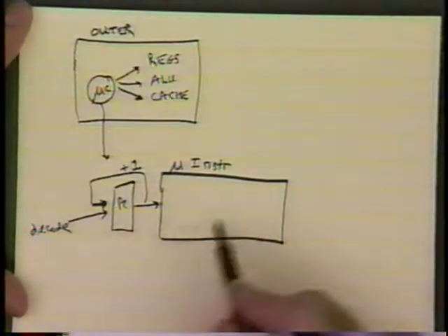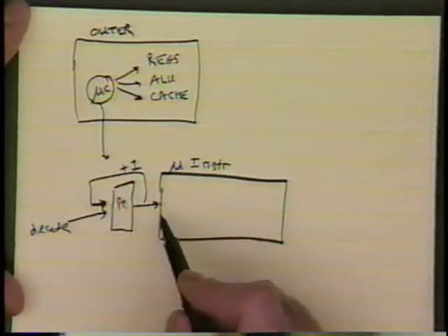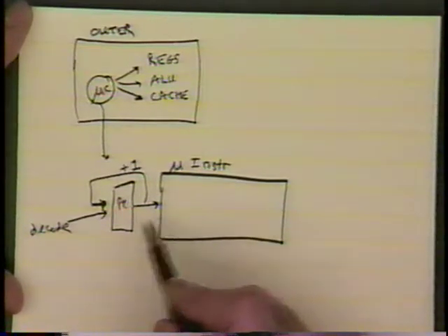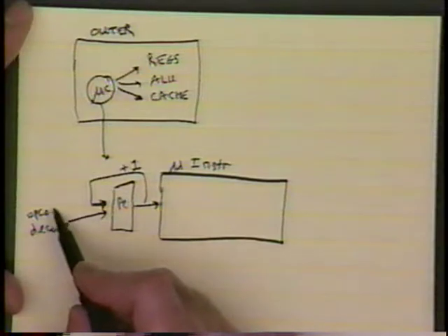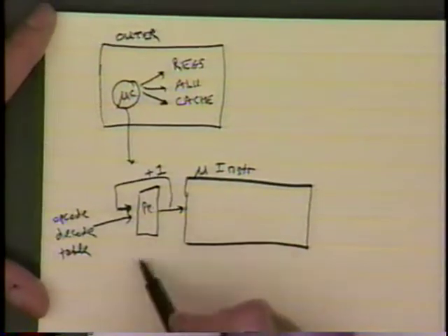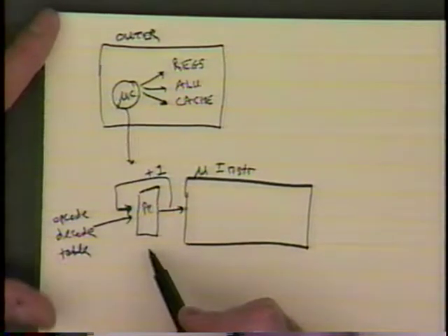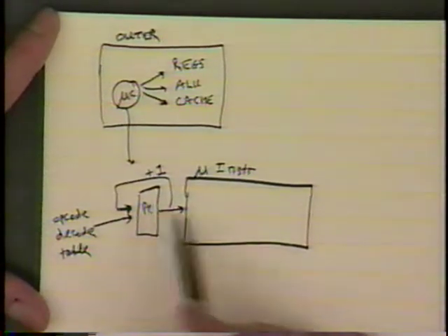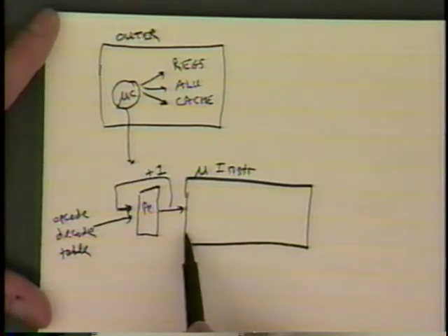One of the things you want to do is to be able to get to the right place in the micro instruction memory really fast based on the opcode. So you could have a built-into-hardware opcode decode table that says, based on that opcode, here's the program counter to start execution from in the micro instruction set.